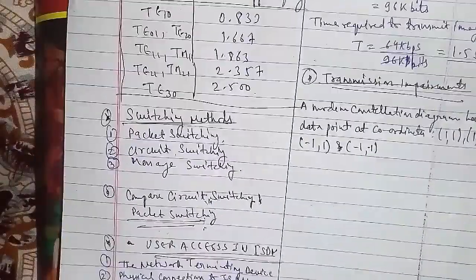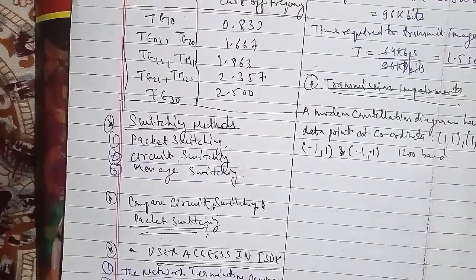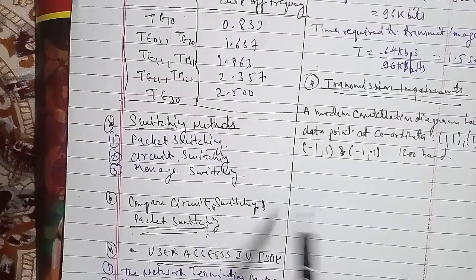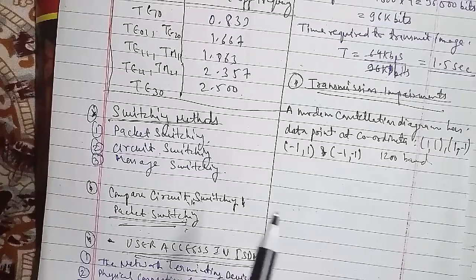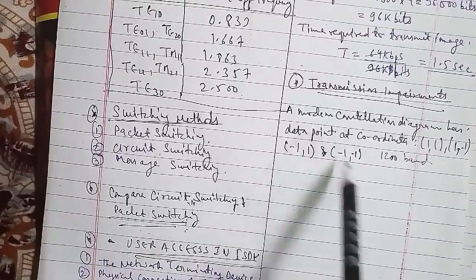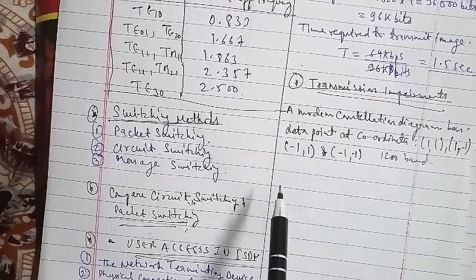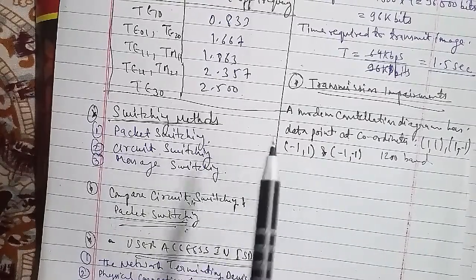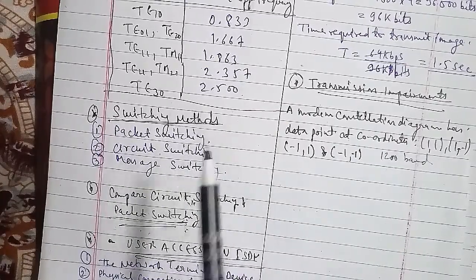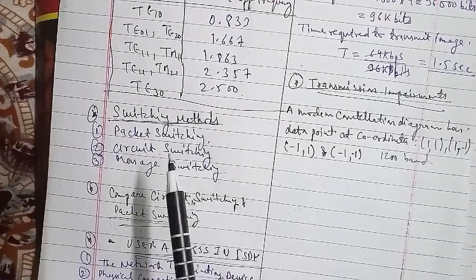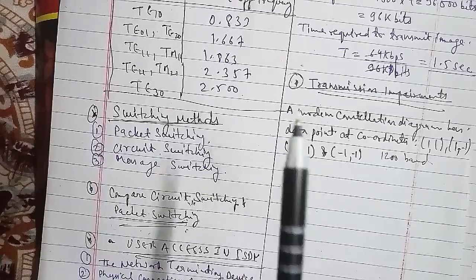So first, the difference between the bit rate and a baud rate is that the bit rate measures the number of data bits, that is zeros or 1s, transmitted in 1 second in a communication channel, but the baud rate refers to the number of signal or symbol changes that occur per second. A symbol is one of several voltage, frequency, or phase changes. The next is that the baud rate is always less than or equal to the bit rate but never greater. And the modem constellation diagram has 4 data points and 4 combinations. Each baud can transmit 2 bits, and QPSK encodes 2 bits per symbol.